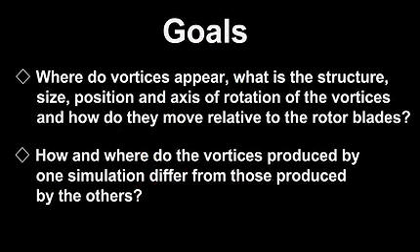To understand the behavior of rotating stalls caused by the separation of flow from the rotor blades in the centrifugal pump, we optimized the visualizations to enable the viewer to answer these questions. Where do vortices appear? What is the structure, position, and axis of rotation of the vortices, and how do they move relative to the rotor blades? How and where do the vortices produced by one simulation differ from those produced by the others?